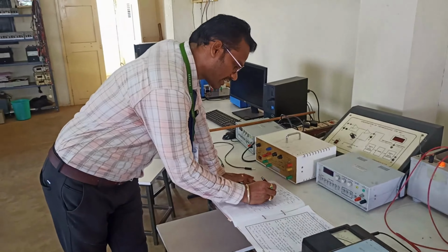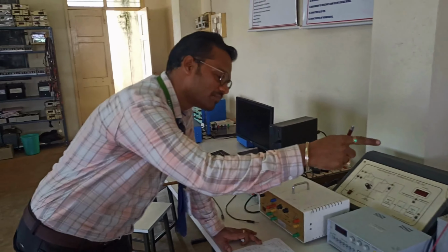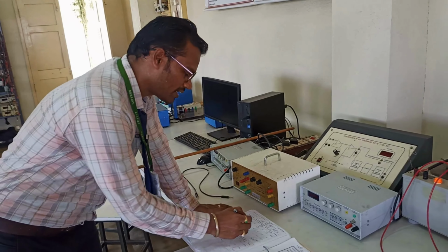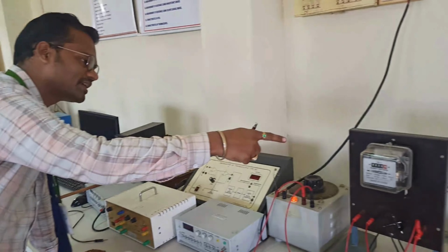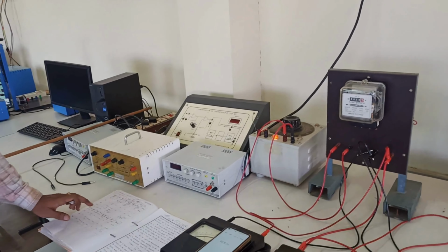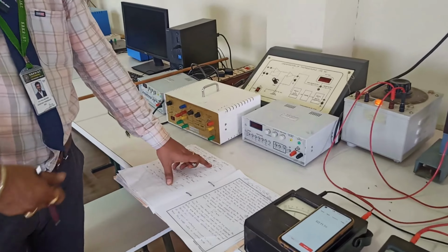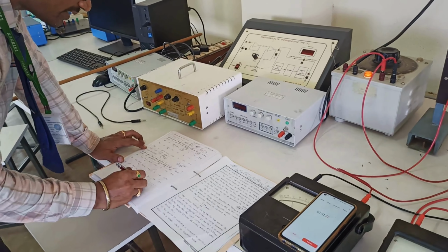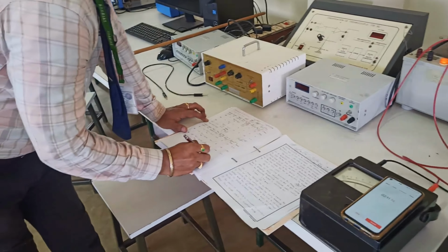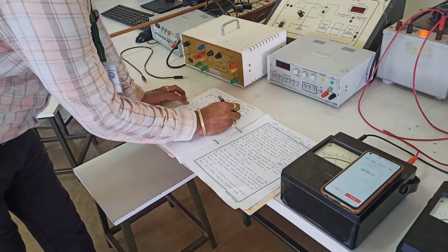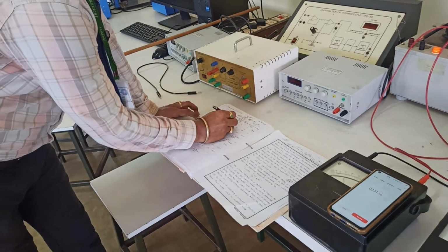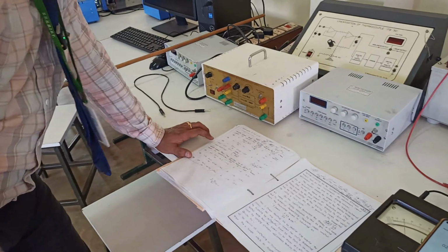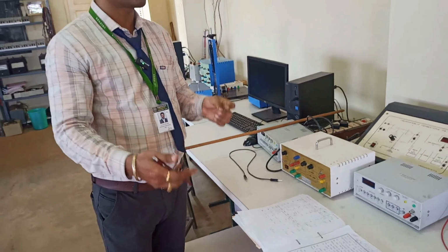Now we want to do the error calculation between the energy meter and the wattmeter. The first watt hour is the calculation from our meter. If the meters are working well, it will give a watt hour calculation, and we already calculated the number of turns multiplied by 1200, which converts into kilowatt. Then you have to find the error. The error formula is E minus ER divided by ER into 100, where E and ER are capital letters. When you do it, 1.18 minus 1.16 divided by 1.16, you get approximately some error. This error we have to reduce.